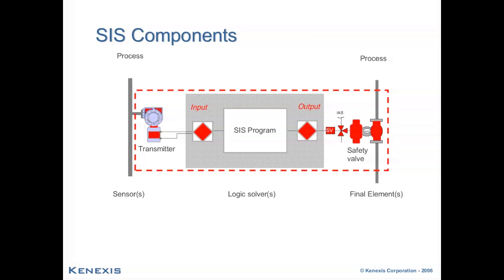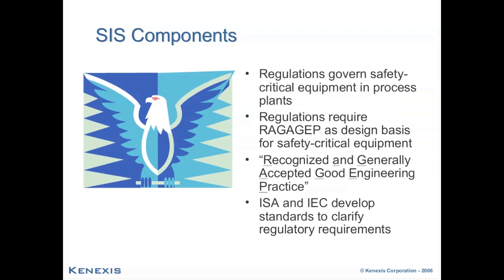It was recognized by the standards making group and the committee that a failure of any of these components could result in a situation where a safety function was inhibited from performing its intended action on a demand, and therefore the standard takes a fairly holistic approach in looking at the overall safety loop and determining the likelihood of success, the likelihood of failure, and ensuring that the system is designed robustly enough, as I mentioned earlier, to meet a tolerable risk target.